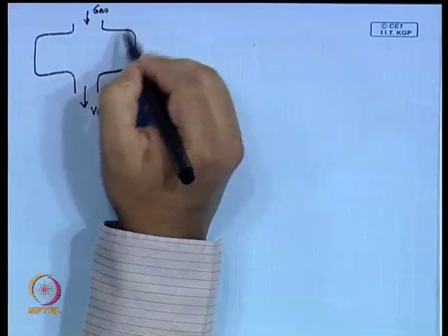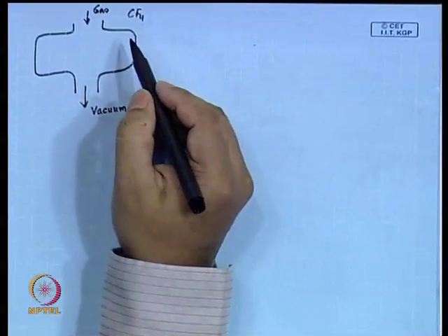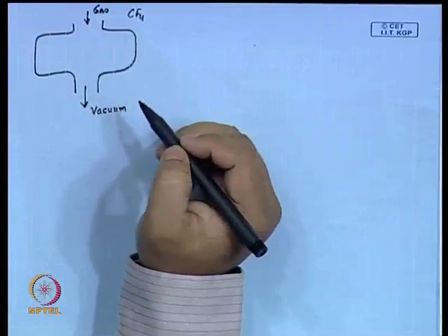A common gas could be CF4, which can be ionized. CCl4 is carbon tetrachloride. CCl4 is used for certain forms of chemical etching. I mentioned those 4 methods. The fourth one, DRIE, uses CCl4. Physical etching is done by CF4. This CF4 would be ionized.